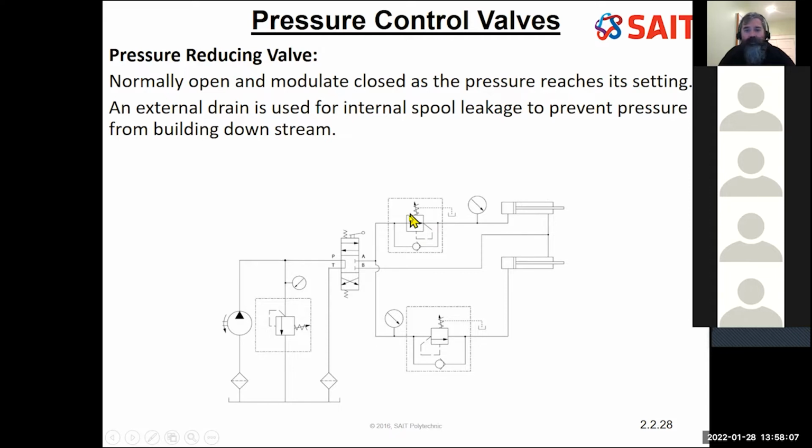Excellent. That valve is now closed, allowing our system to open this valve. This valve here, you can see, is looking at the pressure on the inlet side. As the pressure increases, it's going to open this valve, allowing fluid to go through and extend that cylinder as well. It gets fully extended, maximum pressure builds up until the relief valve kicks in, allowing the fluid to get dumped back to the reservoir. Kind of wasteful in energy, but this is how it works.